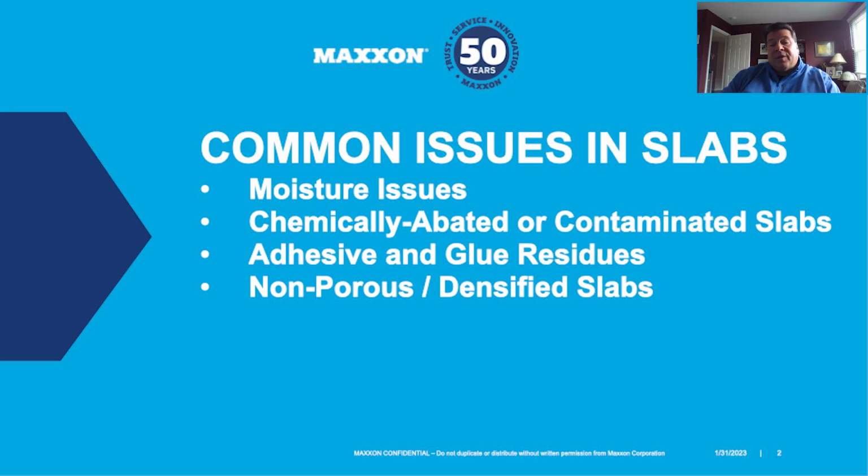When we talk about problematic slab conditions, we come across certain things that have come to be noticed as major issues with the installation of new floor covering. Things like moisture, excessive moisture in a concrete slab, porosity in the slab or lack of porosity, usually caused by slabs that have been polished or densified in some way. We talk about contamination through the chemical abatement process, surface contamination, or even contamination from within the slab itself.